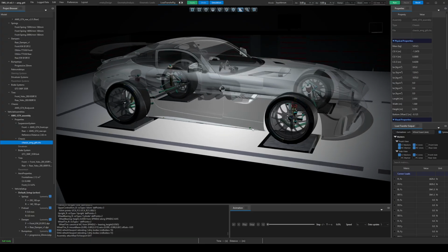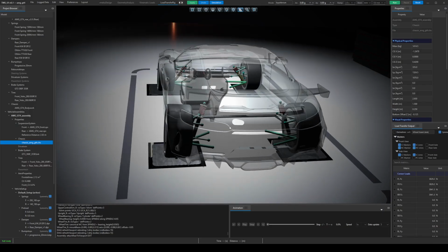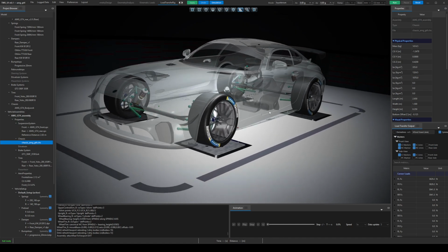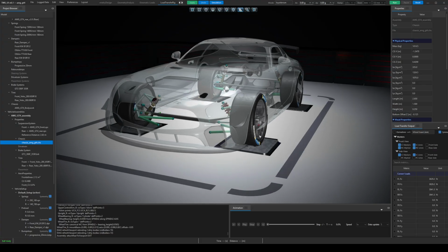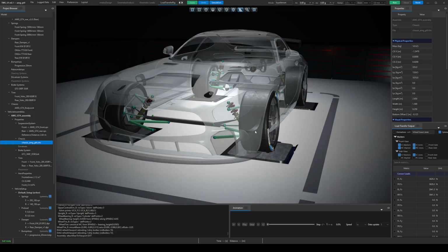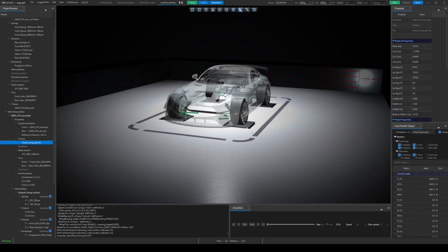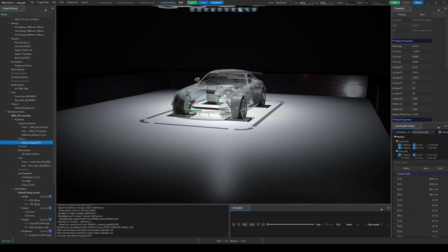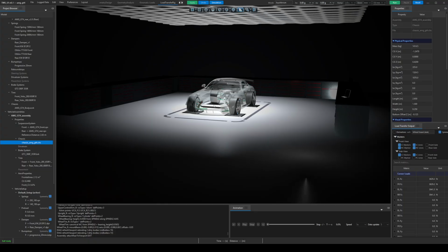Each major component has its own mass and inertia. The upright, brake caliper, brake rotor, and related hardware are represented as a lumped mass. The damper is modeled as two bodies, the damper body and the damper shaft. Springs are represented as one-way force elements with free length. Anti-roll bars are modeled as torsional springs connecting the left and right sides of the torque tube. The blade is represented as a lever arm fixed to the tube, so changing the effective blade length changes the stiffness seen at the suspension pickup point.